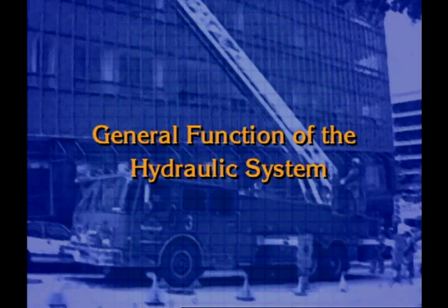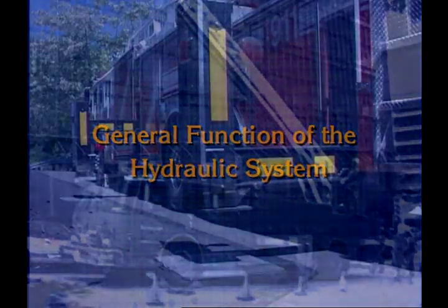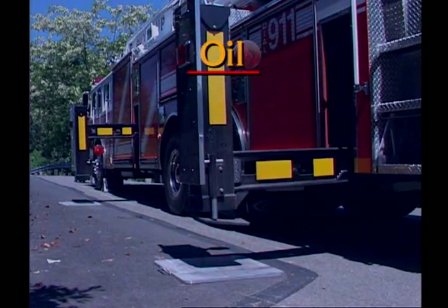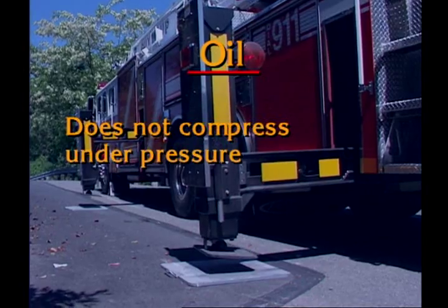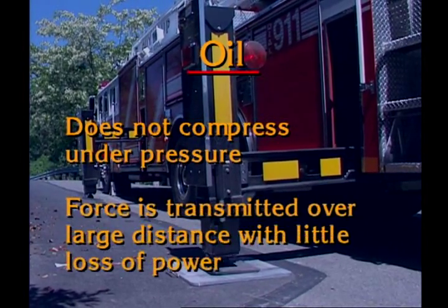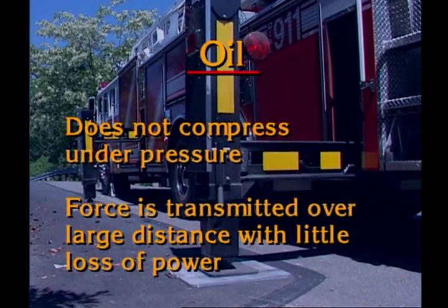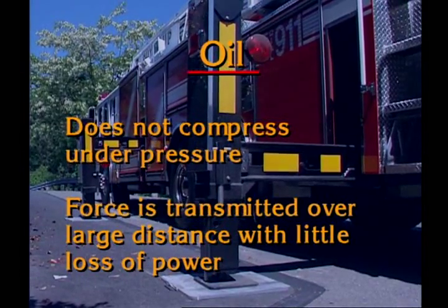In newer aerial apparatus, virtually all stabilizers are hydraulically powered. Oil is the medium used in the hydraulic system for two reasons. First, it does not compress under pressure, and second, it allows force to be transmitted over a relatively large distance with little loss of power.